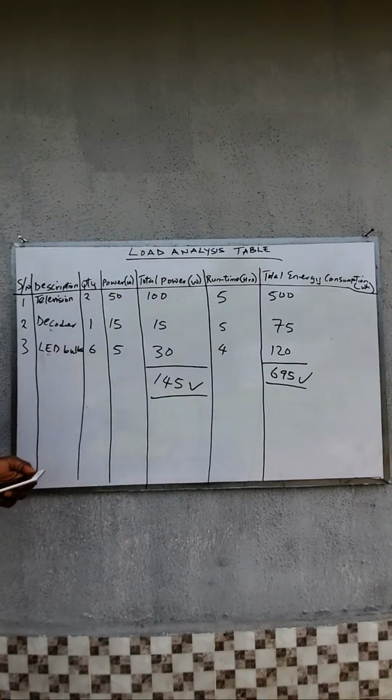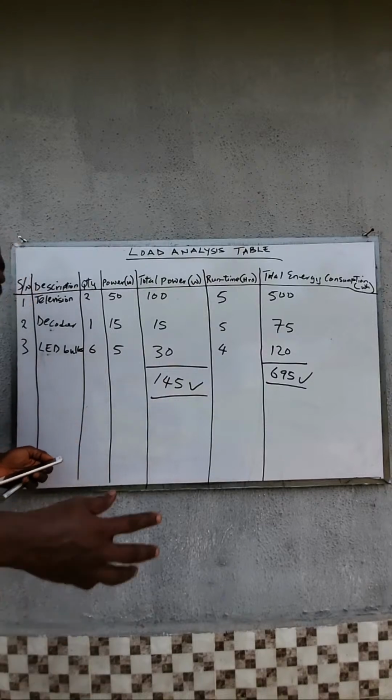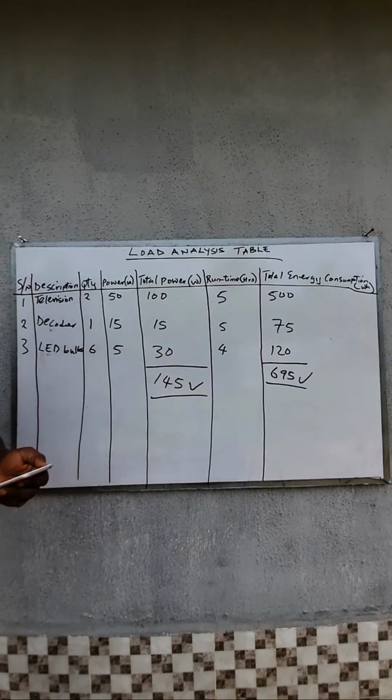It means if in the morning all of them will want to rush to make use of those water heaters, you know the power they will be drawing. Then you have air conditioners. You have other heavy appliances. So you must educate that client that if you want to use solar to power all these appliances, this is what it will cost you. And this is the calculation.